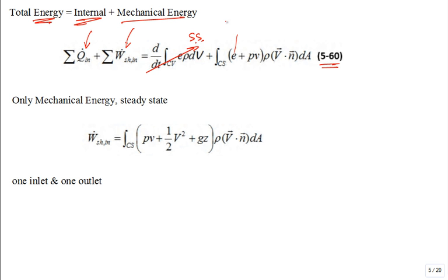E is the internal energy plus the kinetic energy plus the potential energy. The PV comes from that boundary work that gets lumped in. And so when we add the PV there, we get that it's H plus the kinetic energy plus the potential energy, where you recall that the enthalpy is U plus PV. It's nice to go back to firm ground, like, oh yeah, I passed thermo, I understand that energy equation, I understand enthalpy, right? So that's good.